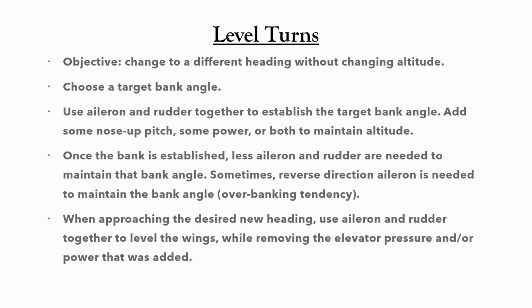As you approach the desired new heading, you'll use the aileron and the rudder together to level the wings, and you'll remove any elevator pressure or power that you added when you rolled into the turn.